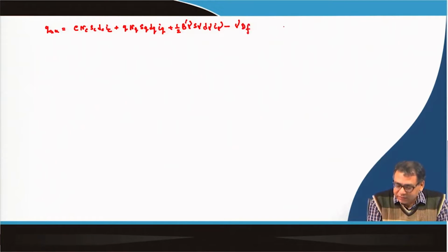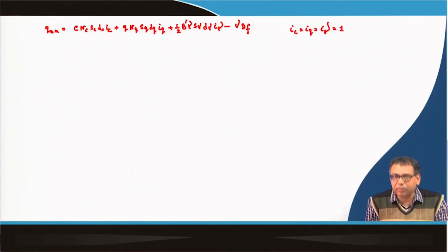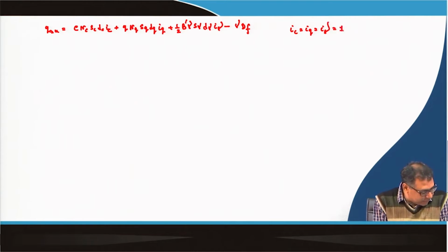Okay, so, as it is a perfectly vertical load, Ic, Iq, I gamma will be equal to 1. So, now let me determine those bearing capacity factors or correction factors.